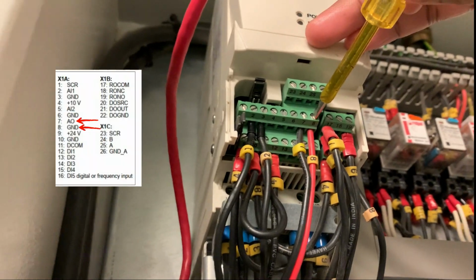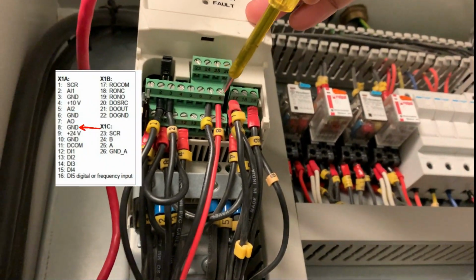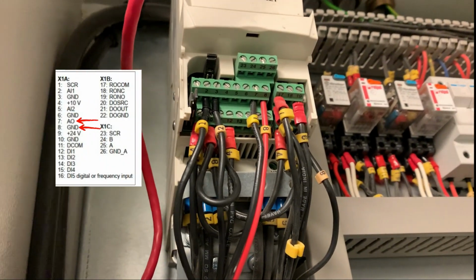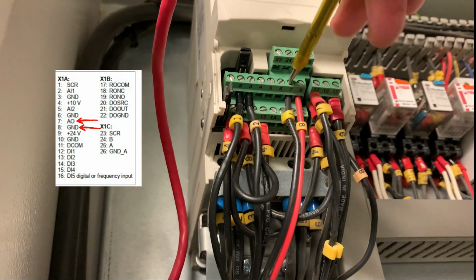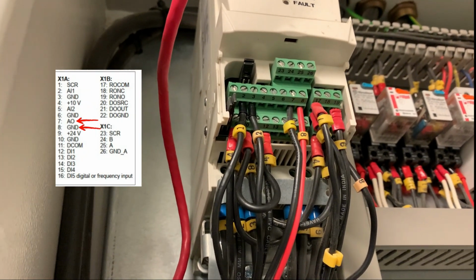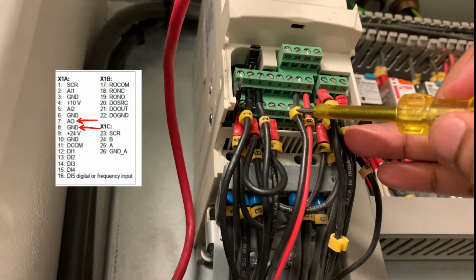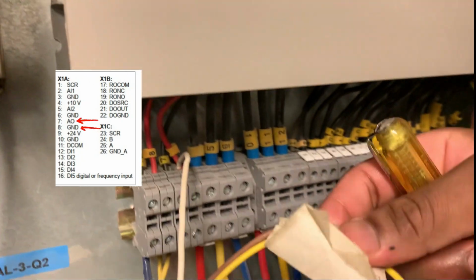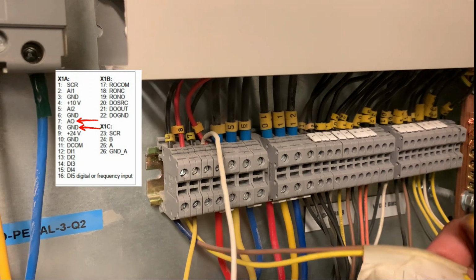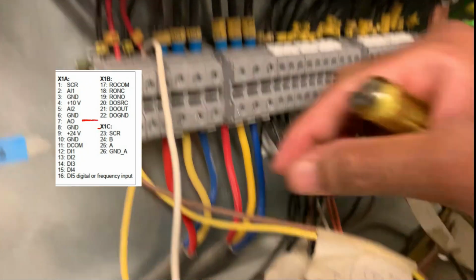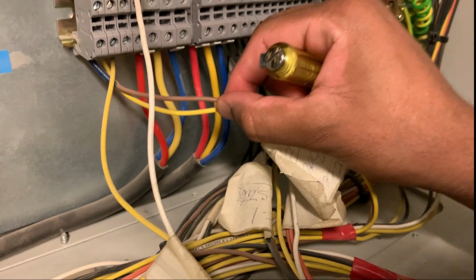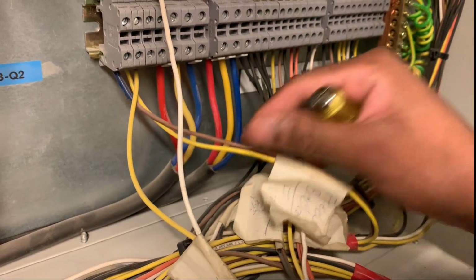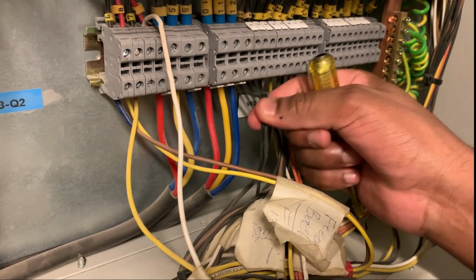Okay, and here the 2 terminals 7 and 8 are nothing but the analog outputs through which we can see the feedback from the BMS that the motor is running. We can check whether the motor is running at 100% or 50%. As you can see, 7 and 8 are connected over here, and there are 2 cables connected, which are also connected to our BMS. So we can read the speed from these 2 cables, and we can give the command and the speed from these 2 cables.